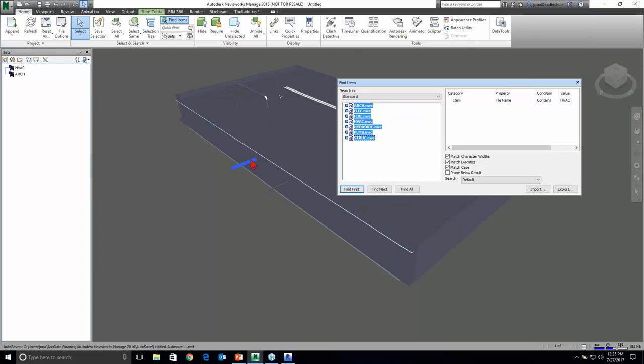So you can see I have some blue highlighted elements here. Click Architectural, click HVAC. We can keep doing this with all of our elements. Let's try plumbing next. Oops, duplicate, rename, plumb. Change this one, PLMB. Find all, and all my plumbing highlights. Right click, update.